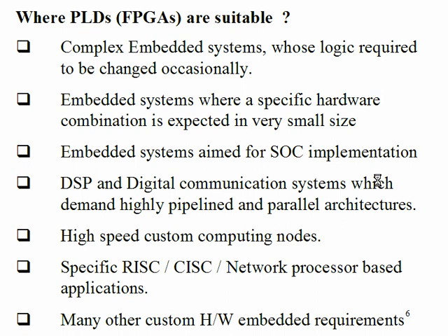Look at this. We know this point: complex embedded systems whose logic is required to be changed very occasionally. This is the main reason, isn't it? Point number one, it is very complex, so I cannot get it done by a microcontroller or some small kind of thing. I need relatively bigger logic. Second thing is I have to change the logic very occasionally. So FPGA is very suitable. Now, can a microprocessor also meet this kind of requirement?